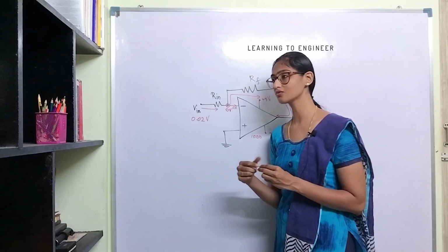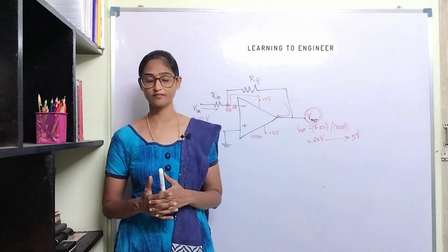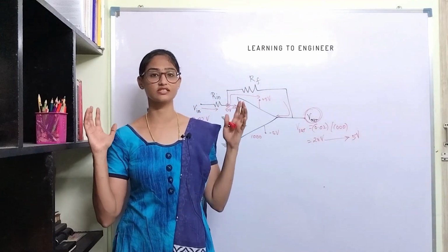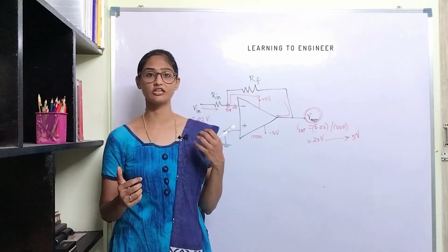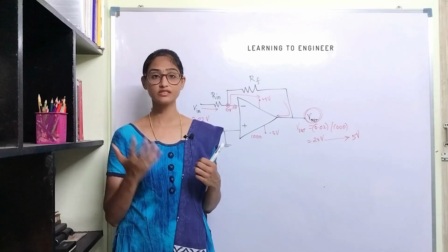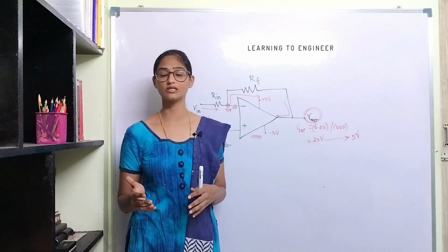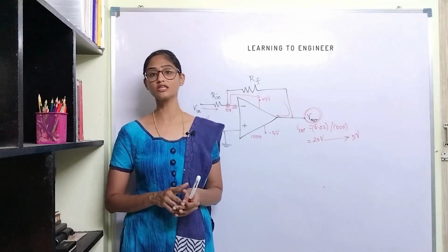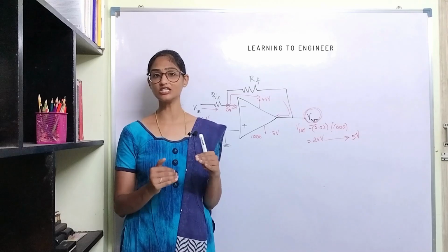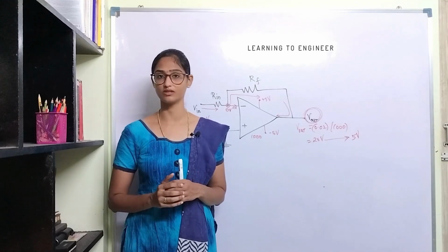So whenever you want to generate a stream of pulses, we use positive feedback, in applications like a sine wave generator, sawtooth wave generator, multivibrator, Schmitt trigger, and so on. You don't have any feedback resistor when you are using it as a comparator, because the objective is to find out the higher of the two signals which are connected to the inverting and non-inverting terminals.